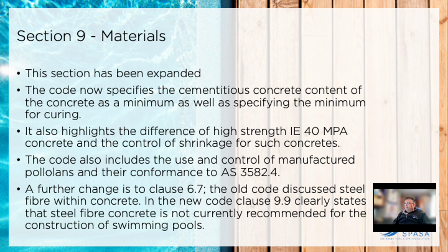The code. So the further change to clause 6.7 is the old code discussed steel fiber within the concrete. In the new code, clause 9.9 clearly states that steel fiber concrete is not currently recommended for construction of swimming pools, which is pretty much, in my view, an obvious answer. I don't know too many companies that do steel fiber reinforcement anymore, because basically the steel fibers, even though they are galvanized, they do tend to rust.